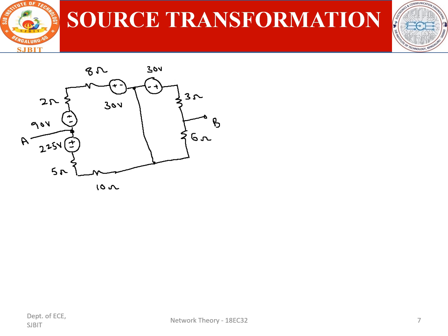So here minus plus, okay, plus minus, different direction. Therefore you can subtract. So the voltage will be, here it is minus plus, and the resistance will be in series. This becomes 60 volt, and this resistance is 10 ohm. Again here the voltage source is positive negative. This is 225 volt, and resistance is 15 ohm, 15 ohm, and you connect this point.